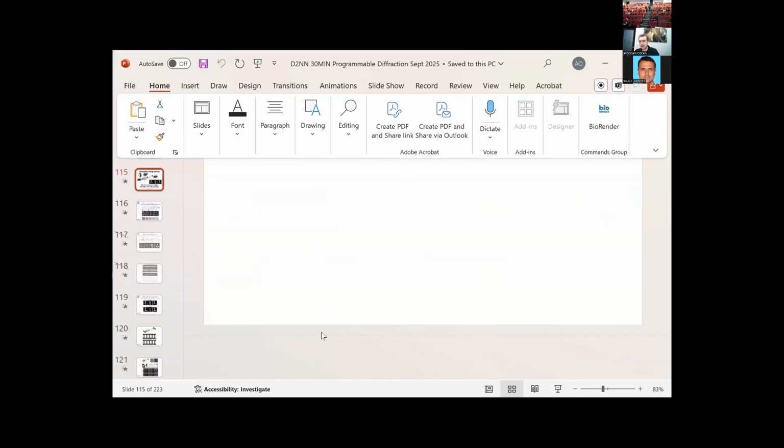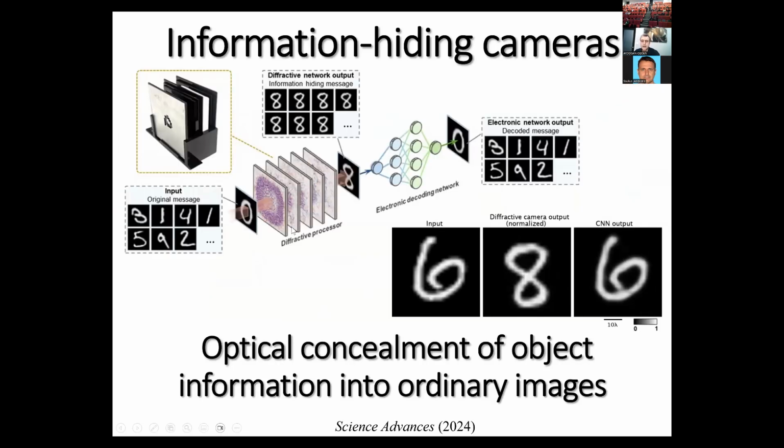Yeah, so the layer-to-layer separation or input to diffractive layer separation can be sensitive, but the biggest sensitivity is not the axial dimension, but actually the lateral dimension. In other words, if there is misalignment between one diffractive layer to the next one, mostly spatially laterally, then you can have some computing problems, inaccuracy.